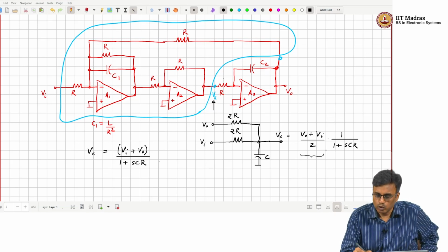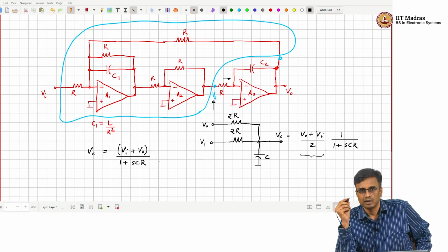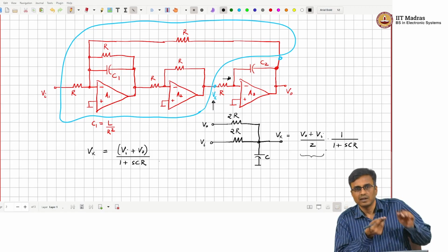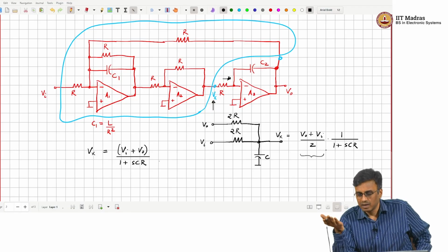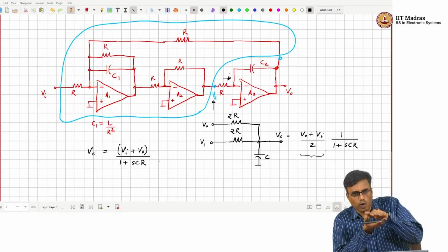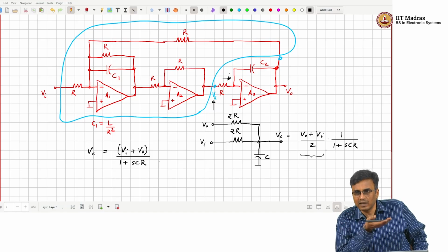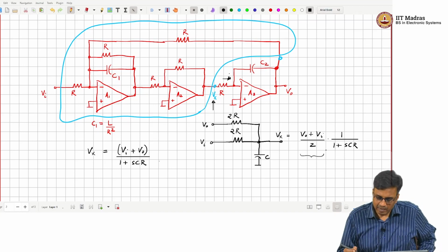So, what should we do to make sure that the same current flows there? The current that flows there in that resistor is what? The voltage Vx divided by the resistance, but the voltage is smaller. So, what should you do to that resistance? You should reduce the resistance so that the current is the same, right.